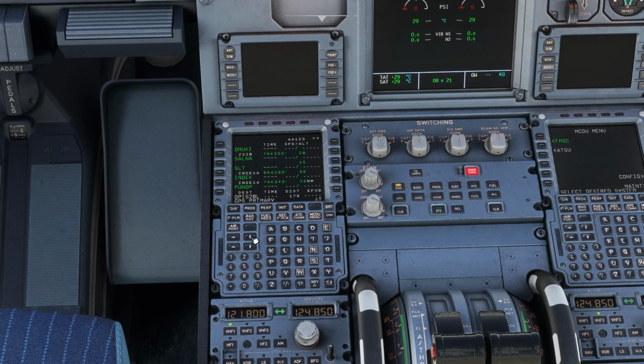Now if you scroll through this flight plan, you will see no discontinuity, and that's it. I was actually looking for top of descent and top of climb, but it's not coming here, but during the flight you will be able to see it. Okay, so now the flight plan is there, but if there is a discontinuity, I have a video on my channel which tells you how to remove the discontinuity. Let's see this example as well.